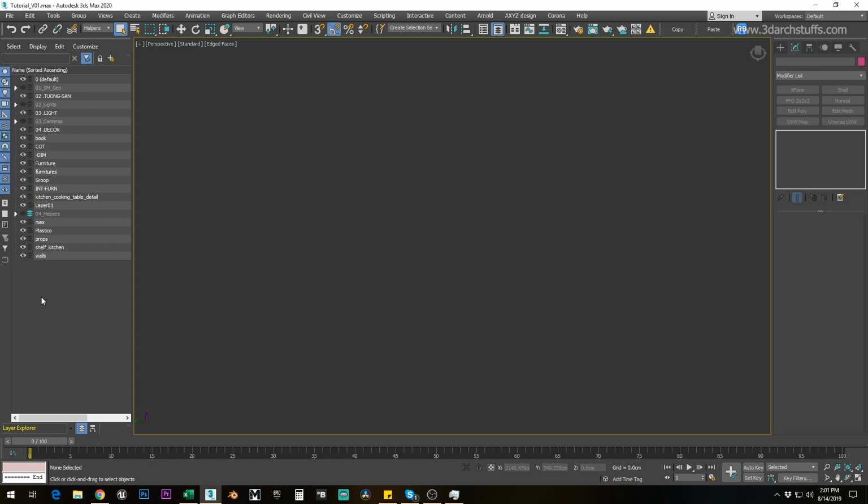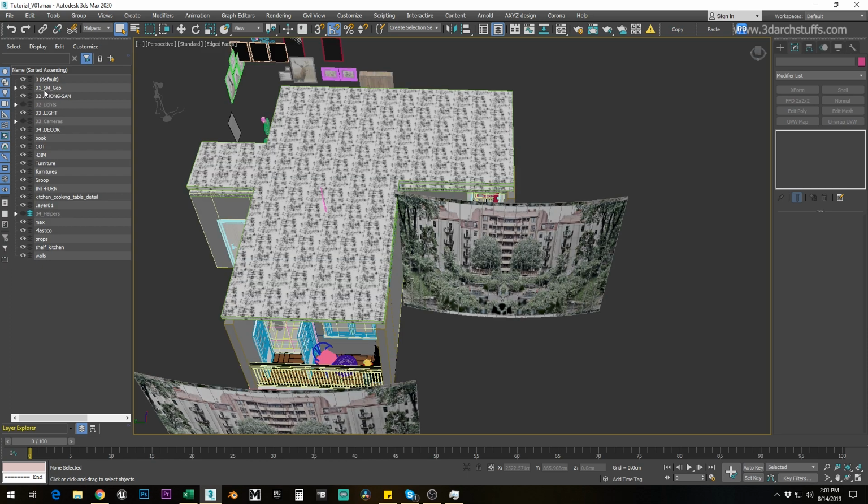So it's a wise decision that you should always open it, and then arrange the helper and group objects inside a different layer, and we will only export the physical geometry that was present inside the group object. After that, we'll show our sm underscore geometry layer, and I will delete all these unwanted layers which we don't need, since they are empty layers.